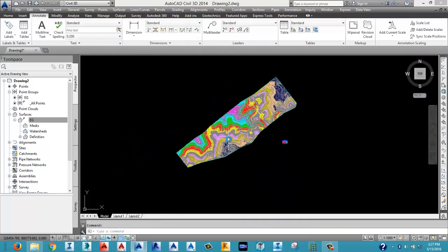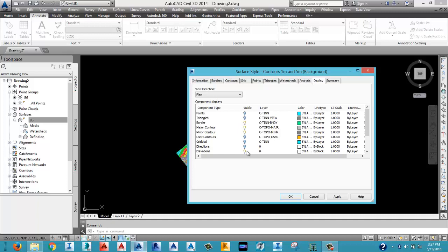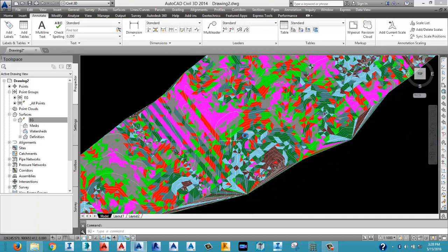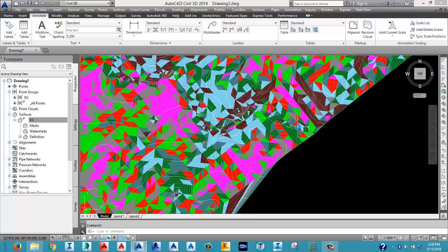Subsequently, this also doesn't come up immediately. I just have to do the same operation all over. Go to edit surface style. I turn off the light for elevation, then turn on the light for slope. You turn off the light for elevation and turn on the light for slope, and you click on your apply and OK. So the slope analysis result comes up for you.